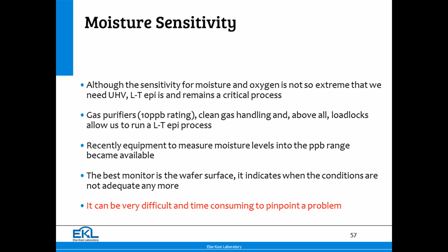And it is the high partial pressure of hydrogen that protects the surface. We do not lose our hydrogen protection at about 450 degrees. This happens in vacuum. With a high partial pressure of hydrogen, we maintain the hydrogen coverage up to 700 degrees or more. That is what protects the surface.